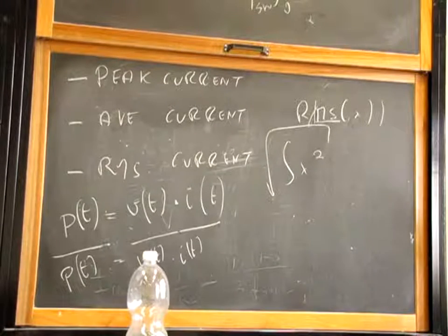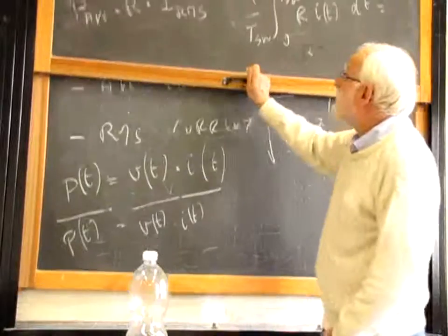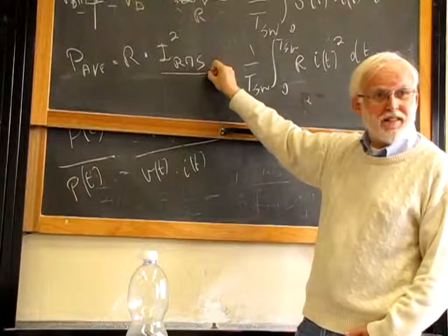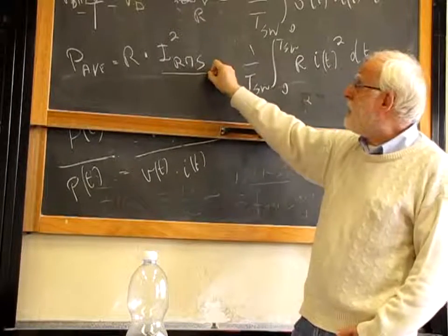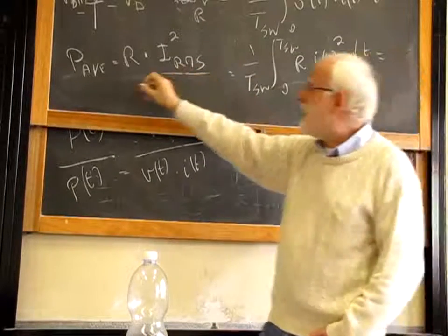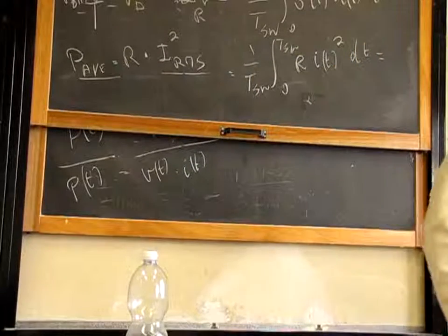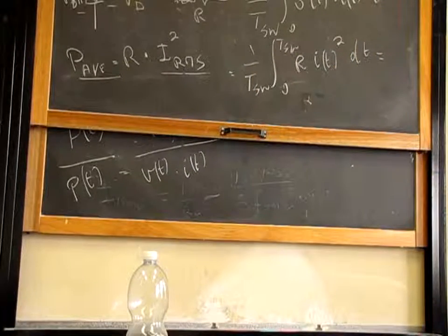By the way, please notice this. I take the RMS current, I evaluate the power using the RMS current, and I get the average power. There is no such thing as RMS power. Too bad, not my fault.